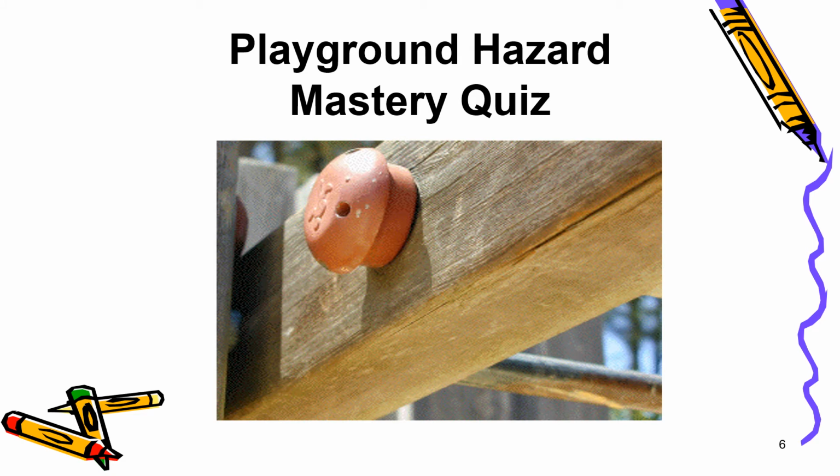Do you recognize this hazard? This slide demonstrates a special protrusion hazard in an overhead climbing ladder. Anytime the diameter of a protrusion increases as you move away from the initial surface, the potential for a hook-like effect occurs. This protrusion fails the protrusion hazard test because it causes a hook-like effect that may entangle children's clothing.